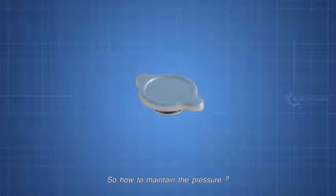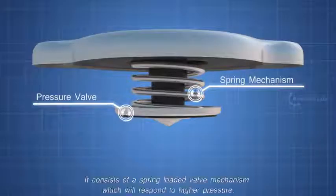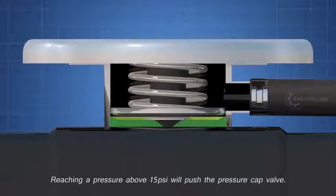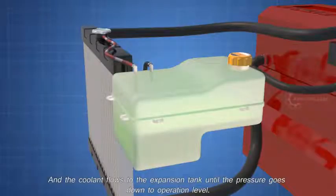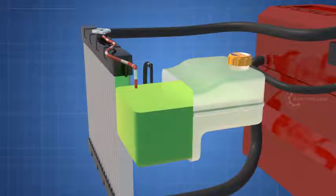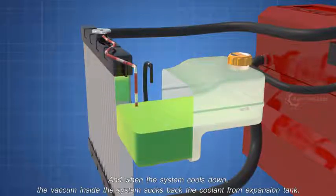So, how to maintain the pressure? Here comes the role of the radiator pressure cap. It consists of a spring-loaded valve mechanism, which will respond to higher pressure. Reaching a pressure above 15 psi will push the pressure cap valve, and the coolant flows to the expansion tank, until the pressure goes down to operating level. And when the system cools down, the vacuum inside the system sucks back the coolant from the expansion tank.